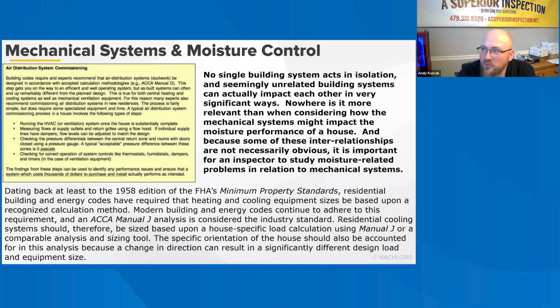To provide improved moisture removal and energy efficiency, 2-speed compressor heat pumps with variable speed blowers should be considered. These systems operate at the lower capacity much of the time, providing enhanced moisture removal and more efficient operation. Such systems offer the greatest benefits in areas with long cooling seasons and are also a good match for 2-zone systems because they can effectively handle single or dual zone operation.